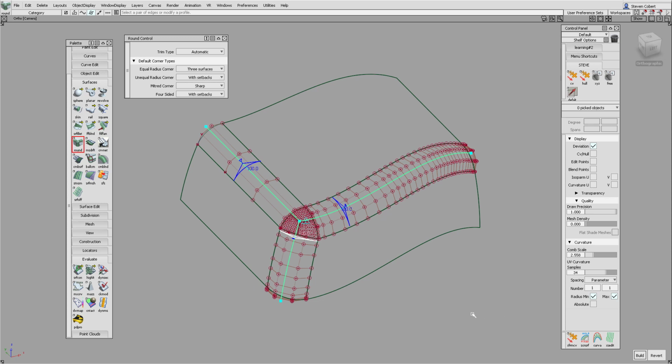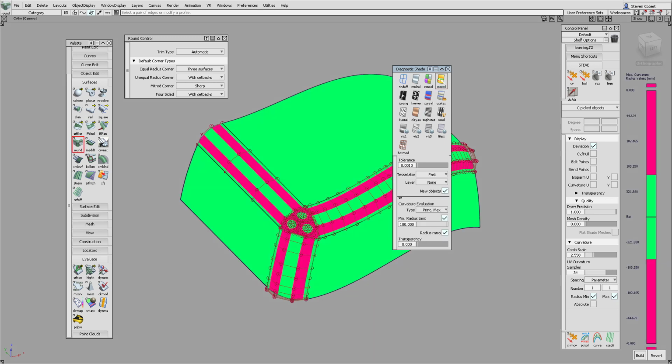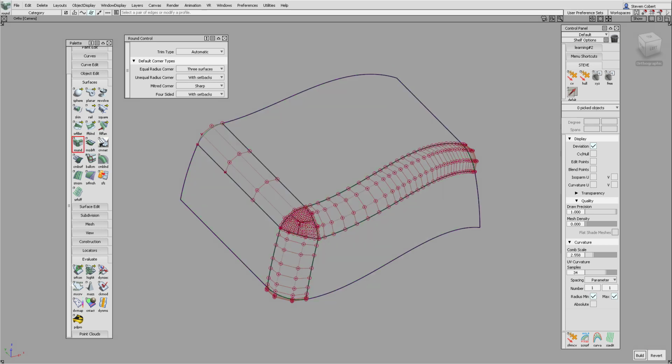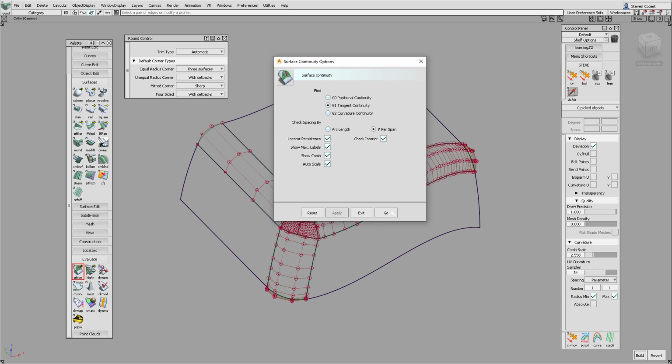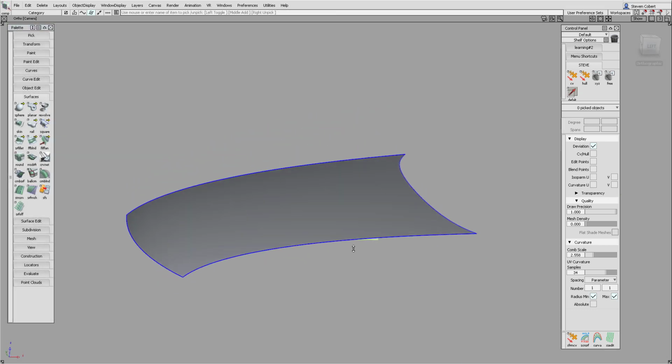You can see that when we analyze the corner radii using the principal maximum display, the corners are not 100% accurate. Round creates a fillet of degree 3 only, which means that the curvature cannot be accurate, certainly for larger fillets. Round gives us no control over the degree or spans or the end conditions. The continuity of the edges may not even achieve G0, let alone G1, so for A-class surfacing, using round is out of the question. However, it sometimes can be used in A-class work for packaging checks.